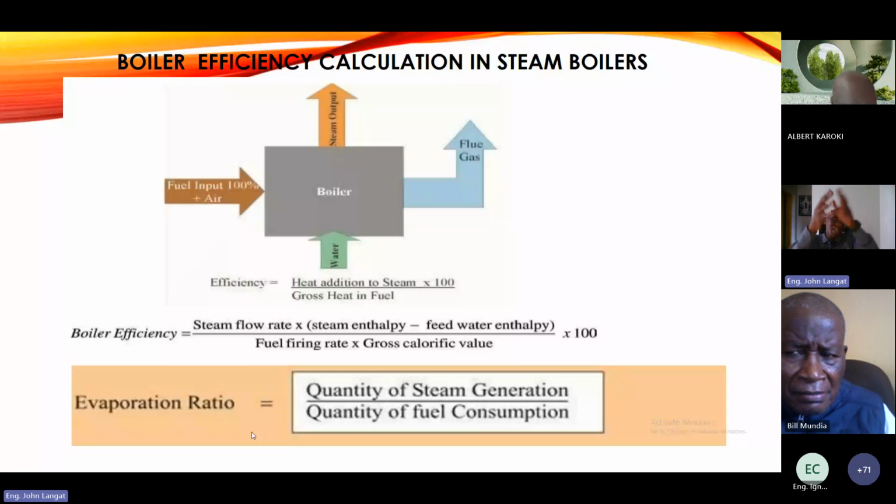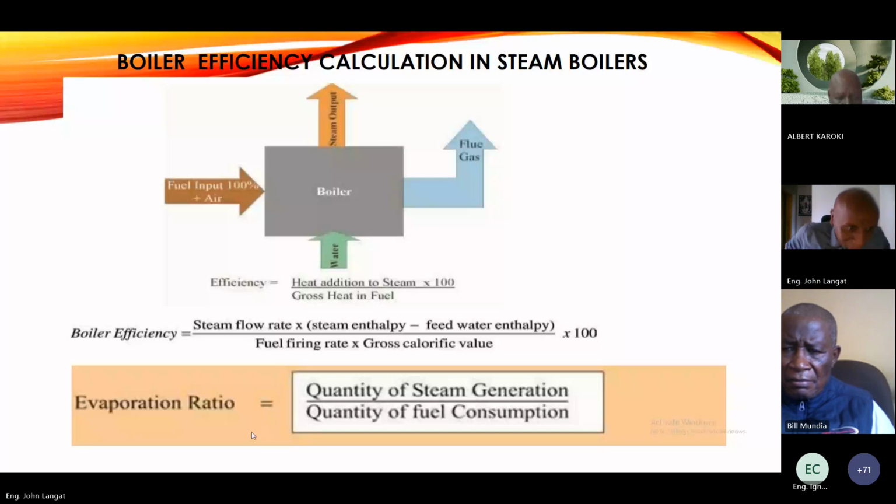That's when you can open the boiler and see inside: is there soot accumulated around the fire tubes? What is the water quality of the condensate? Are there total dissolved solids? Are they doing blowdowns? What's the condition of the furnace? What's the condition of the ID fan? Those are things you cannot see during operation because this thing is closed. But if you go there on a Monday, then the next day on Tuesday, when they are in operation, you would be in a position to take these measurements.